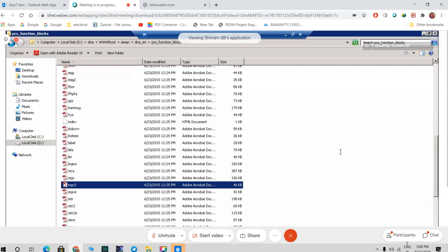When we use TD and TDF in PID. No, that is for if you want a derivative action, then you have to use this TD and TDF actually. Usually derivative action is not used in many other controls. Maybe in speed control and some other where any feed forward action is required, there only we will be using this TD and TDF.